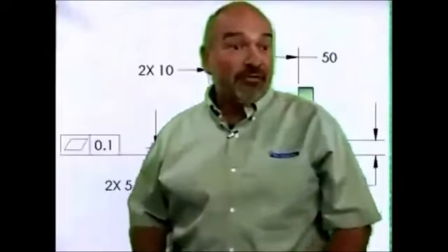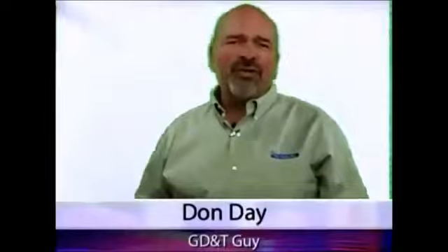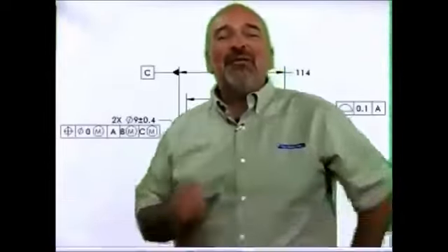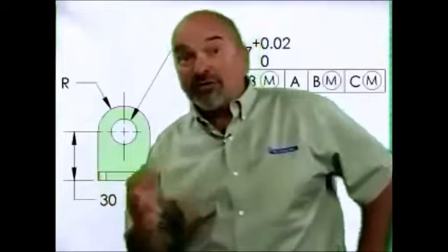This month's tip is entitled Apply Profile of a Surface to Surfaces. It really does matter where you place a geometric tolerance. Often it can change the meaning of the drawing. Other times it's just plain wrong. Profile of a surface is frequently applied incorrectly.